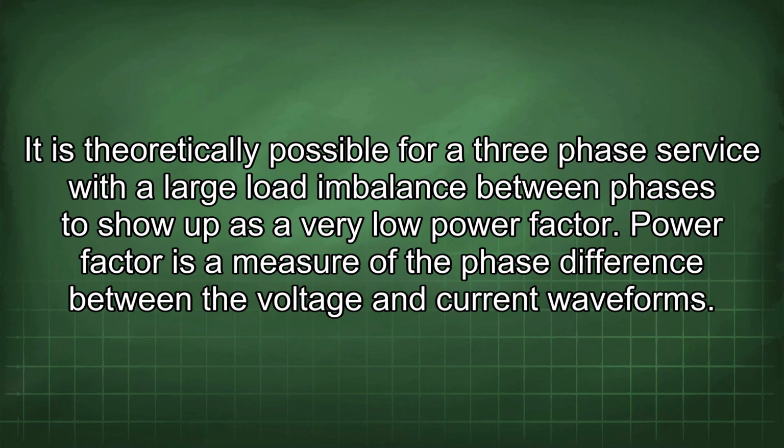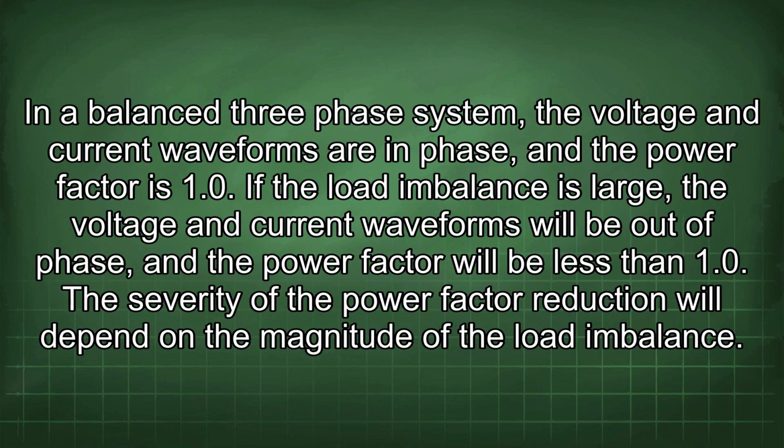It is theoretically possible for a three-phase service with a large load imbalance between phases to show up as a very low power factor. Power factor is a measure of the phase difference between the voltage and current waveforms. In a balanced three-phase system, the voltage and current waveforms are in phase, and the power factor is 1.0.